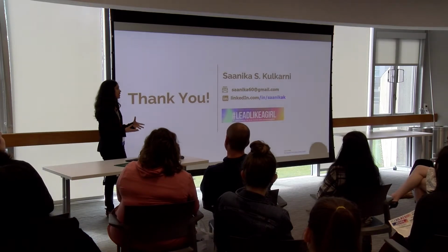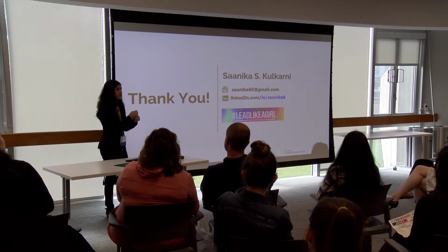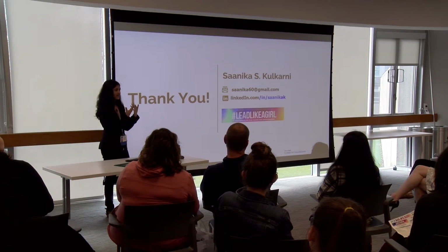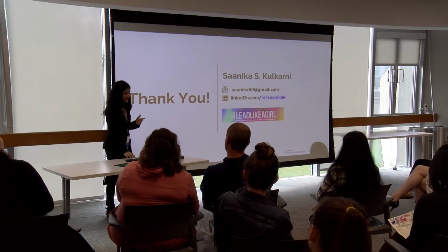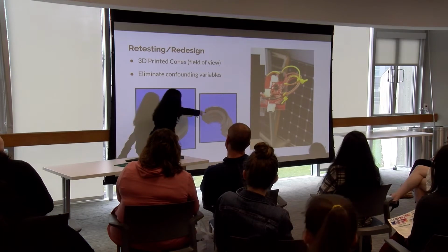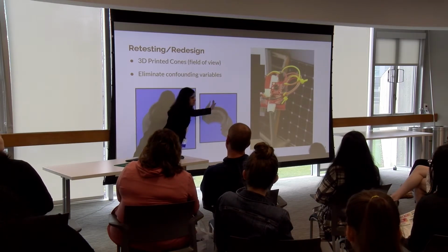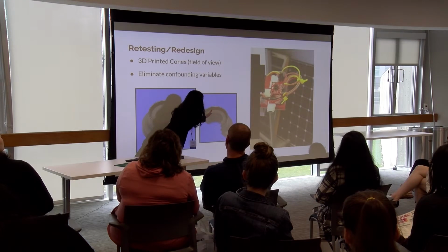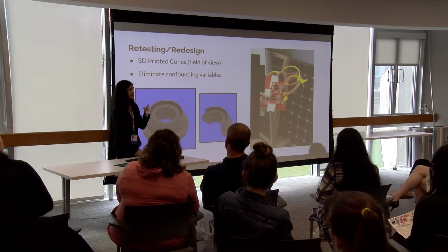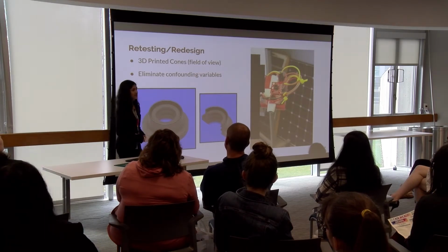And so I wanted to narrow the angular field of view, because in order to get a precise data point from a certain location or coordinate in the room, I need to funnel all the light in, so I need a tunnel for it to pass through. I can actually go back to the slide. I had to design this, which is a cross section, and these are ridges. As the light strikes, it bounces in and goes to the sensor. So there was a very intricately designed cone that I put on the sensor.